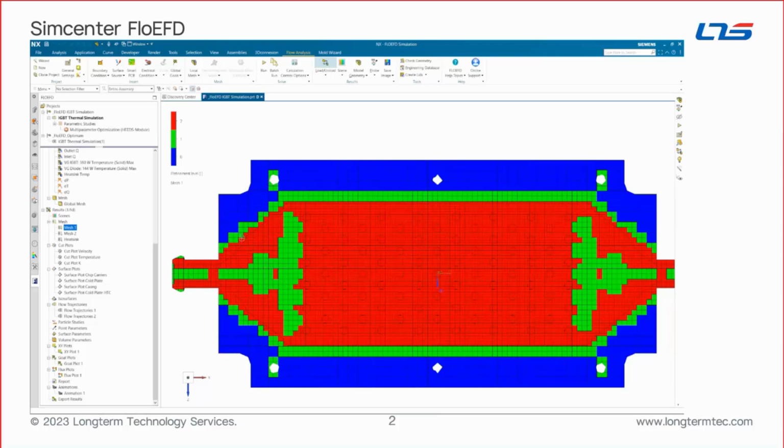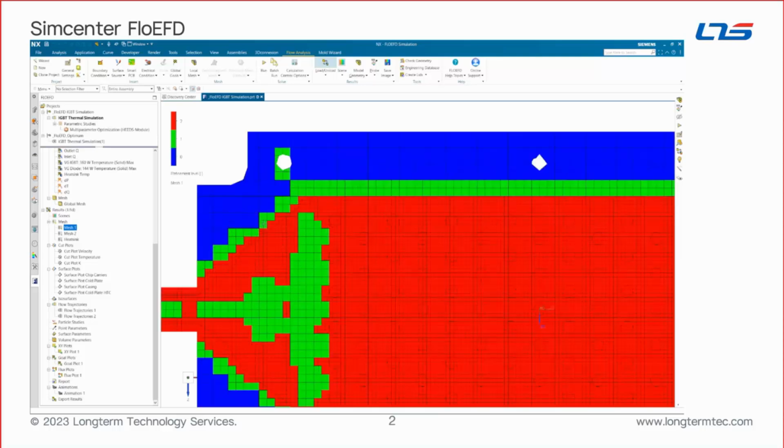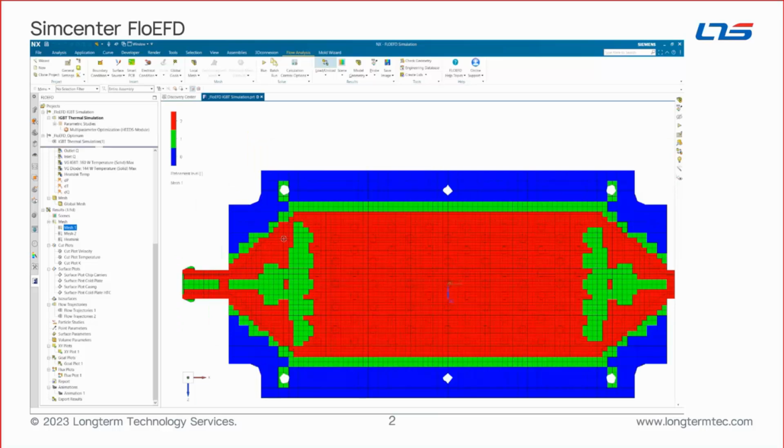And notably, the mesh refinement cannot skip a level. It can only go from 0 to 1, 1 to 2. You cannot have a level from 3 to 1. So it's very important for solver robustness and the convergence behavior.